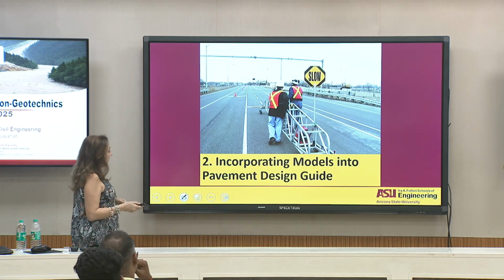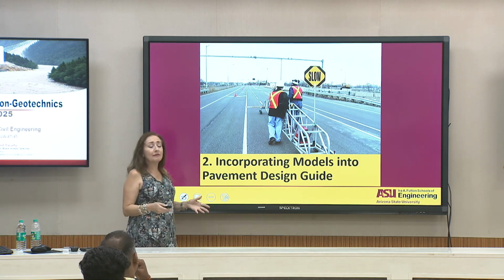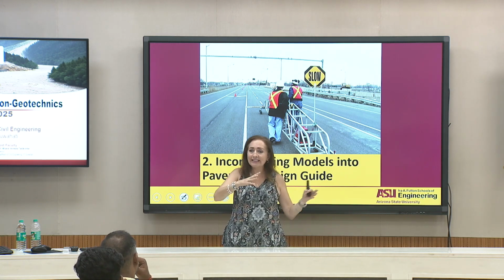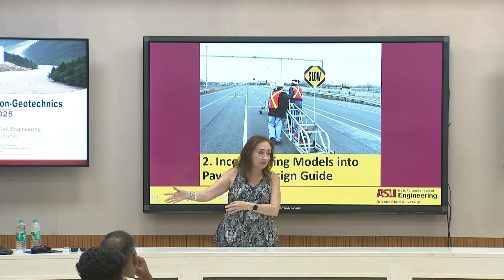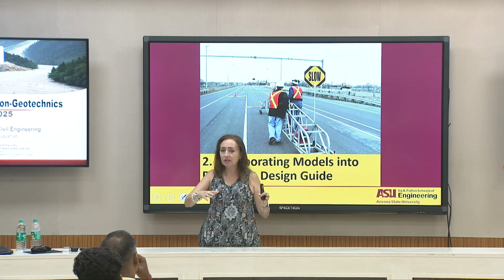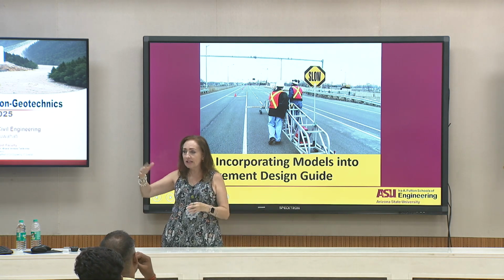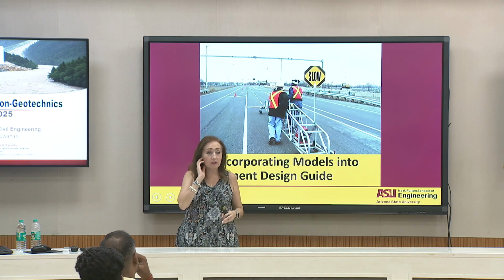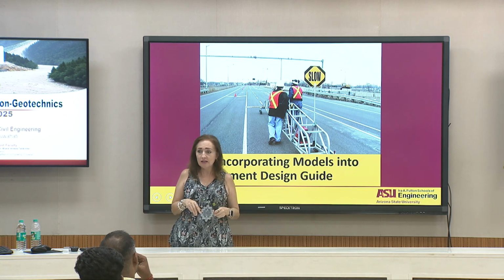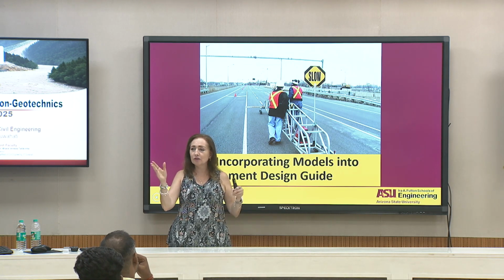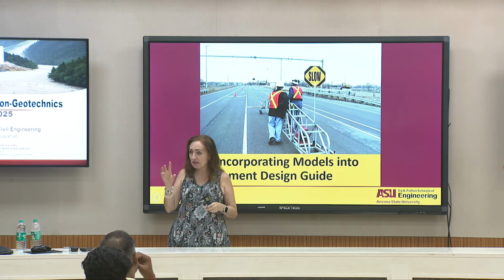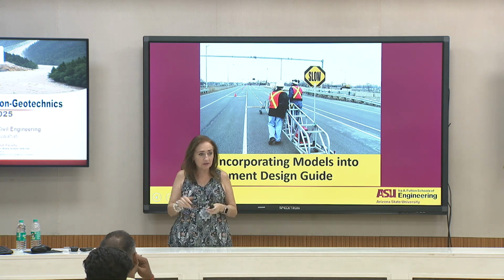So now we do have a value for the volume change, but we were also able to stochastically estimate everything that I've been showing right now, right? The temperature, the infiltration, then the TMI. And now you have variability associated with that, all the way to the suction profiles and soil properties. We even included variability for the soil properties, okay? Because even if I tell 3 of you, please measure the PI of the soil, you're going to give me 3 different numbers, right? So even associated with the laboratory testing, you're going to have some variability, okay?